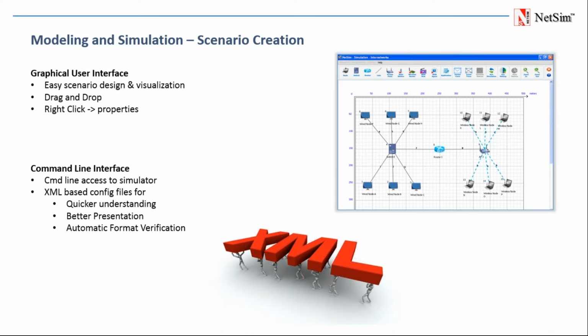So this is modeling and simulation, where a scenario is created. User systems having less memory may face issues while creating a large network scenario in the GUI. So for this purpose, we allow the user to write the scenario in an XML file. This is suggested only for advanced users, and the Netsim support team usually assists the users when writing such a scenario.